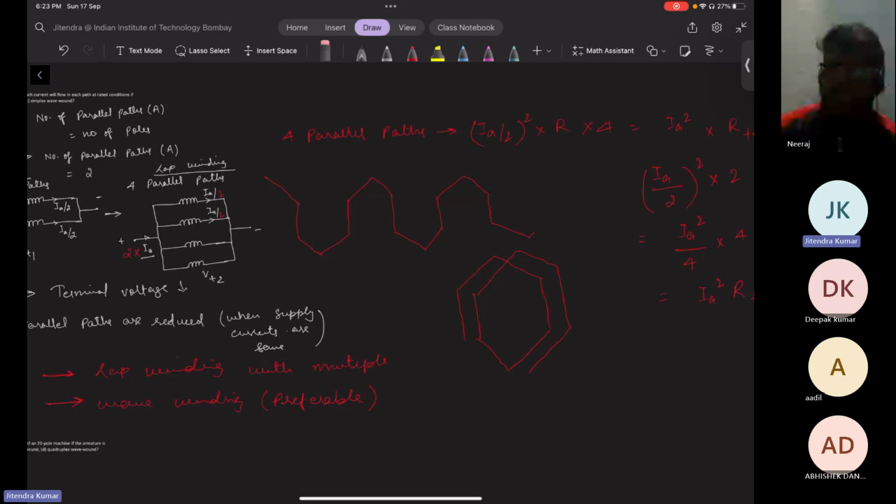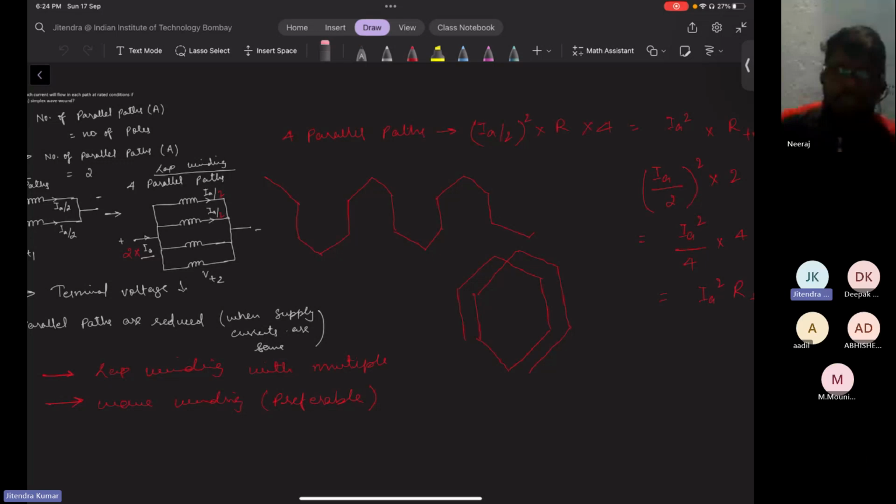Circulating current, yeah. As you go ahead with paralleling the coils or paths or windings, you will have to face the issue of circulating current. It is inevitable. You cannot avoid it. It will be there. So how to deal with that? Does everyone agree that circulating current will flow? And why does it flow? Because it is very difficult to maintain the exact amount of induced voltage in each parallel path. So even if a slight mismatch is there, a circulating current will start flowing in the path, right?